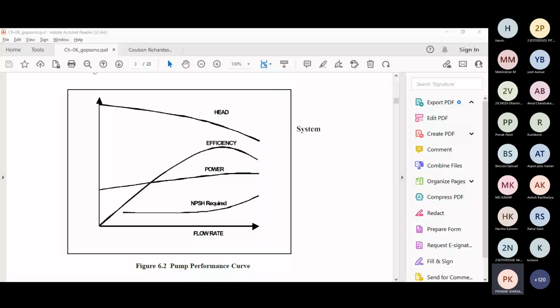So you are saying that with viscous material, like slurries, you can go with the open impeller. But I would recommend that for higher viscosity material, you should not go with the centrifugal pump. Rather, if possible, go with the positive displacement pump. If your flow rate is less, then it's okay. Otherwise, if the viscosity is very high, you should not go with the centrifugal pump. It might also choke the pump. Or you have to go with the jacketed pump.